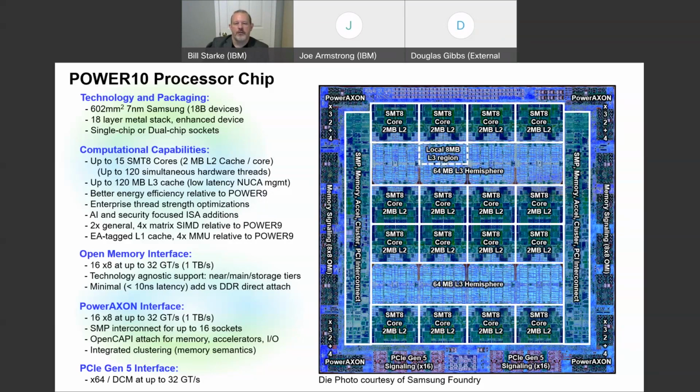Yeah, as far as affinity, historically, I think maybe those of us who've been around long enough to remember Power 7, we definitely had some challenges on Power 7 that we very aggressively addressed as we transitioned to Power 8. A big structural component of addressing that was going from what we called a 3-hop topology to a 2-hop topology.